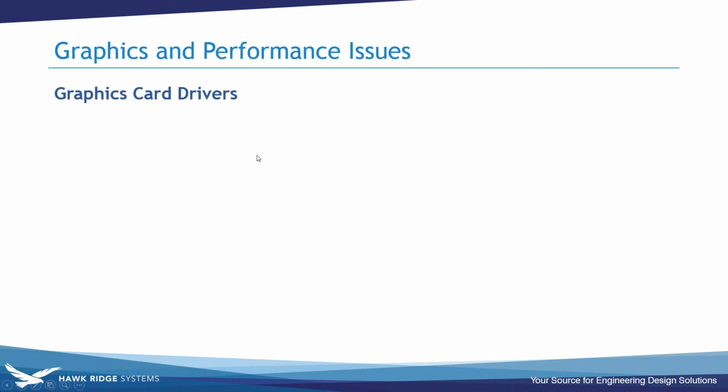So to start off, SOLIDWORKS has certain graphics cards and drivers that they certify. And using a non-certified card and driver can cause graphical and performance issues, and sometimes can cause certain features to function incorrectly. So one thing to note is that the latest or most recent graphics card driver isn't necessarily a certified one.